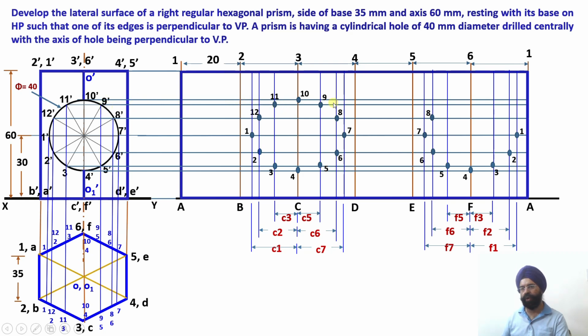So through this locus line, you intersect it with this particular vertical locus line for F5. Just see, this is F5. So this is my point 9 over here. This will give me point 10 because this is the horizontal line through 10 dash, and this is vertical locus for 4 and 10. Just see, this is vertical locus for 4 and 10.